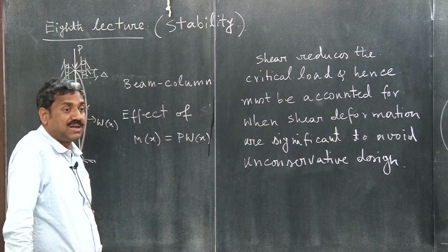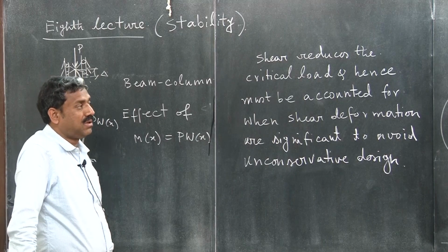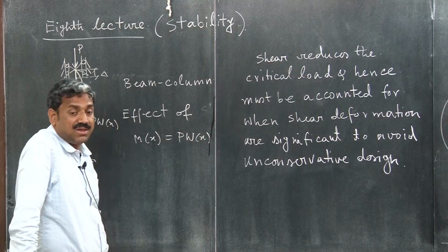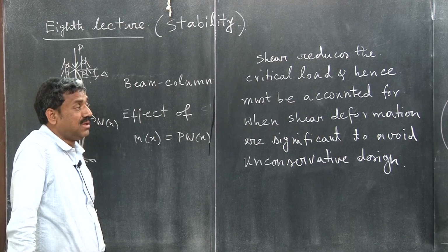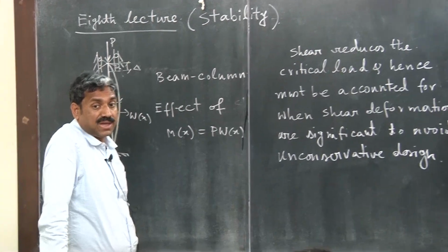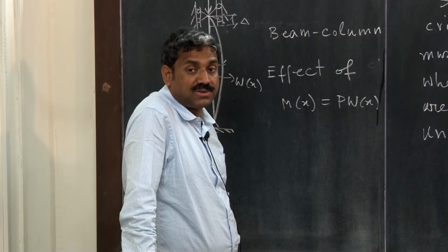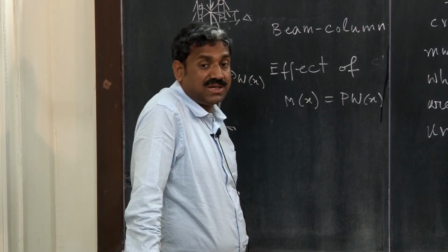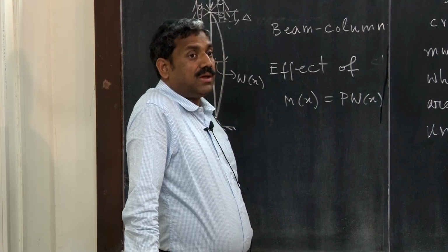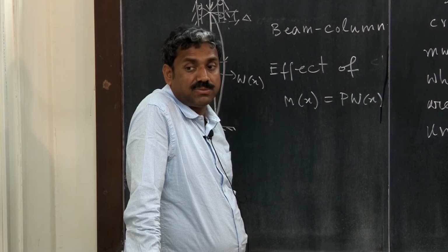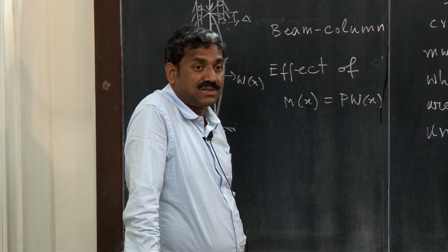So, what we have learned is that shear deformation reduces the critical load. In fact, around the 90s, or even before that, in the late 80s, lots of shear deformation theories were coming for plates and other structures, including Reddy's shear deformation theory. Now, for most shear deformation theories, the first order shear deformation theory is by Timoshenko in beams, and in plates it is Reissner-Mindlin.